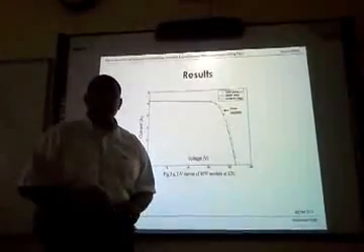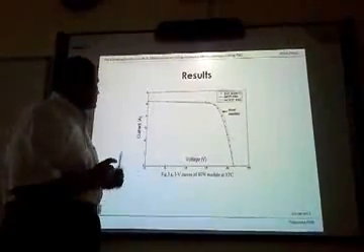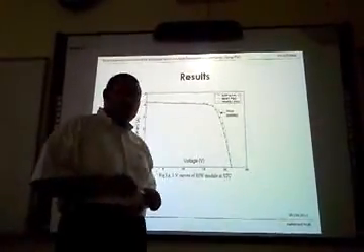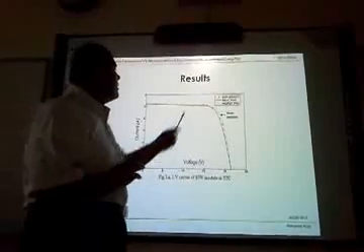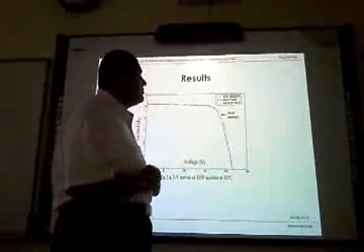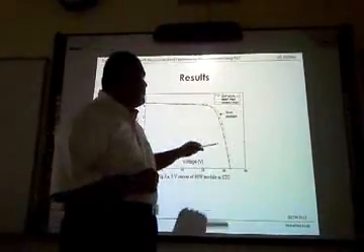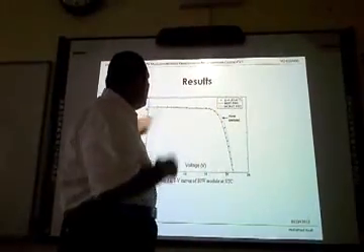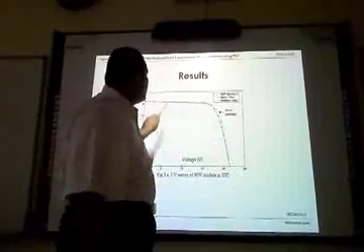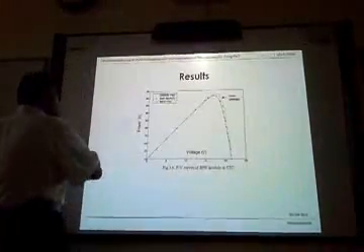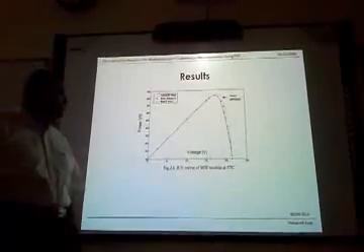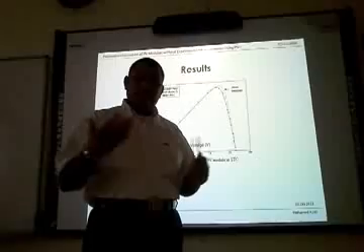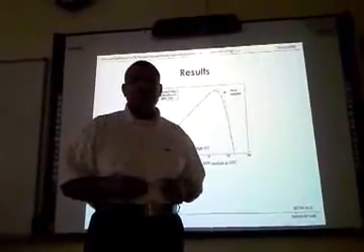These parameters are utilized to plot the IV curve of the PV module. We have an 80-watt PV module. We plotted 3 curves: the exact curve from the experimental datasheet, the continuous line which represents the best obtained solution, and the dashed line which represents the worst obtained solution. We repeated the curve for the power voltage relation. We can observe that PSO gives results which are in good agreement with real data.